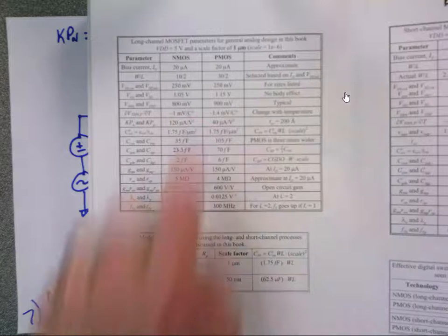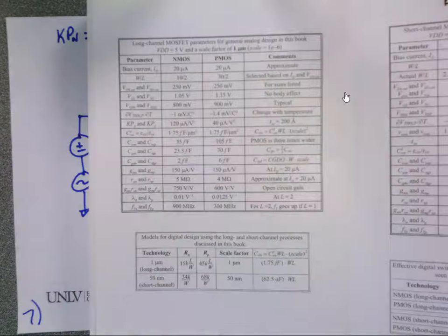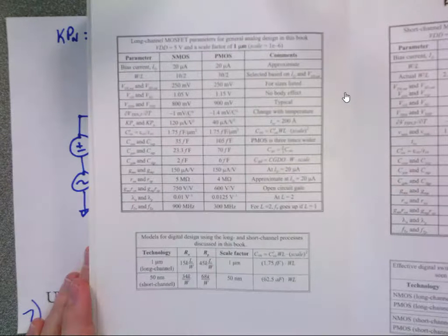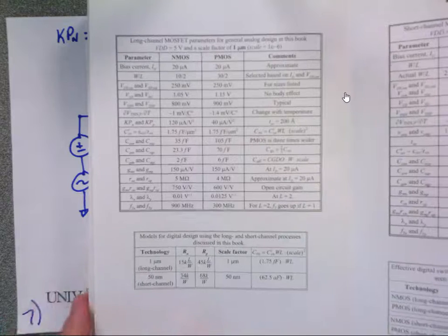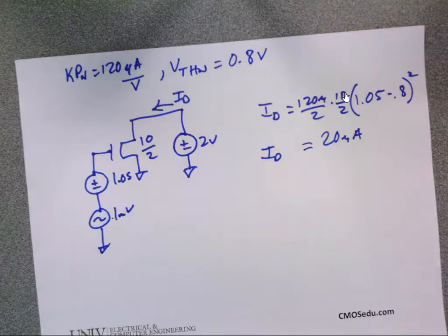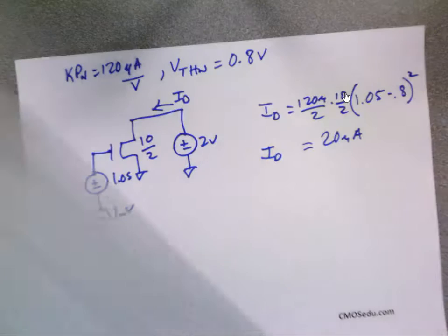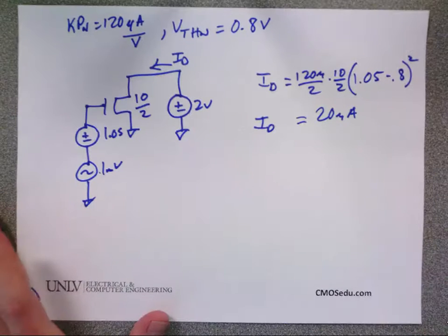No. I could increase the size. Yeah, then it can't. So you can't go above the 20 if you keep the VGS the same and the size the same. I mean, it'll go up a little bit as I just showed, but there's a phenomenon called breakdown, that if you push it too hard, it'll break down. Okay. Is everybody cool with that DC sim?